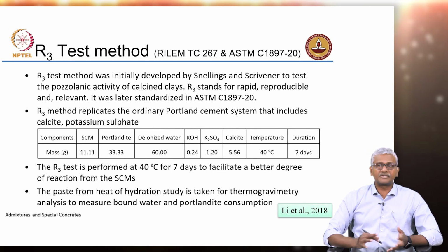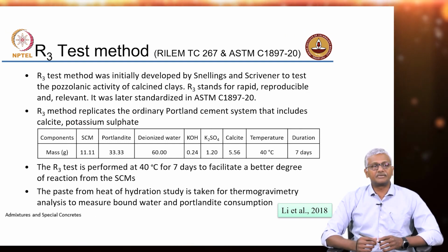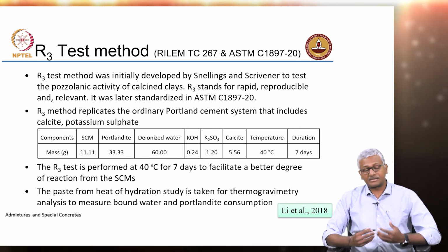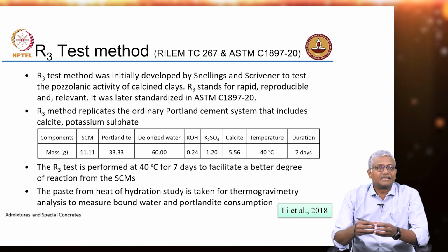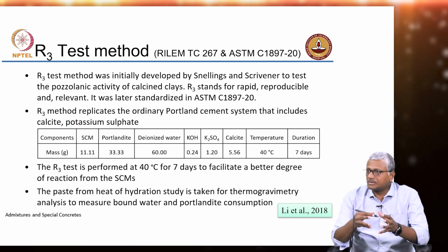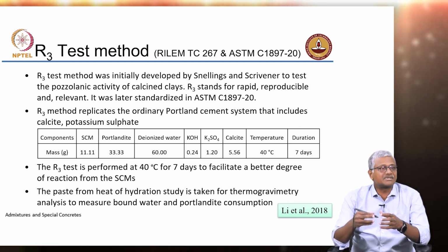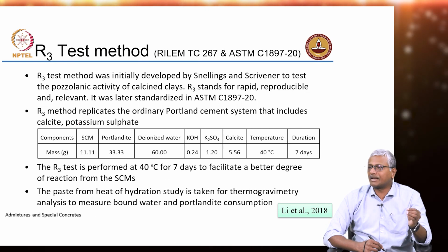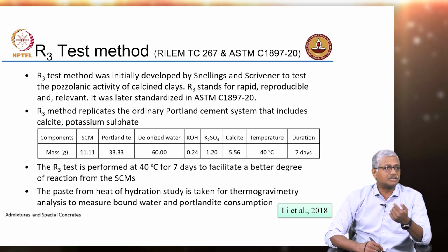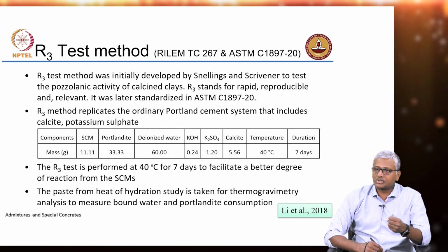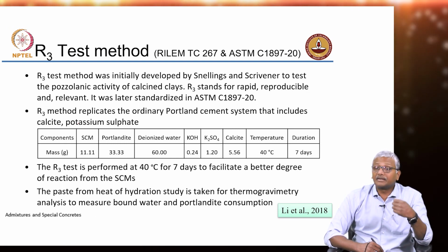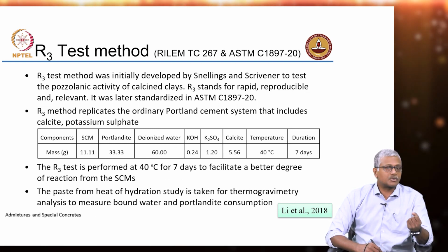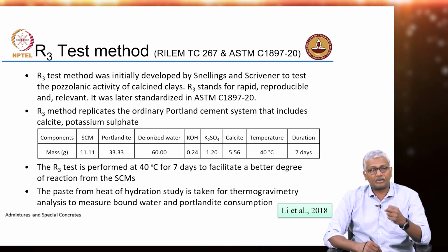Now, based on all of these different background test methods that I talked about, there is a general consensus that's come amongst the researchers that we need a combination of different test methods to come together to give us a clear indication of the reactivity. There is no one single test that can actually help us understand reactivity. So, one needs a combination which looks at lime depletion, which looks at strength enhancement, which looks at heat evolution during the reaction and so on.